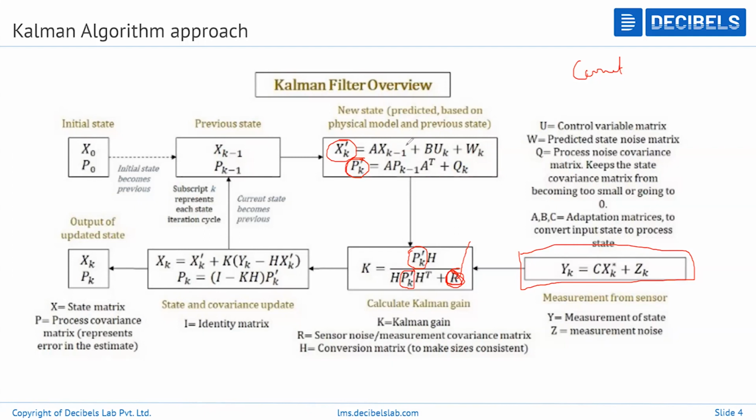We can say the theoretical model is a digital twin of the cell. Initially I was saying that if you represent a cell behavior in a mathematical form, we call it a cell model. That cell model is not 100% correct. It also has some error, and that error is represented by the covariance matrix. You can say it is the error in estimate.